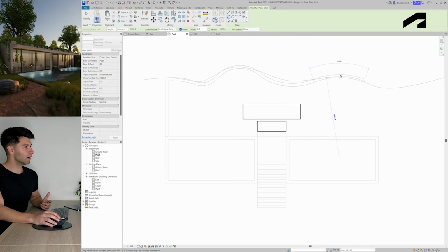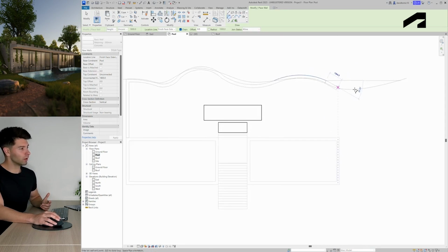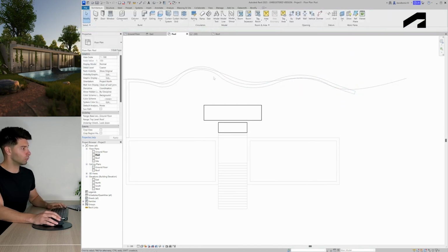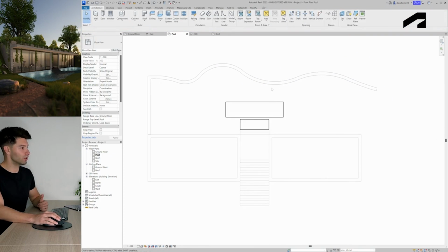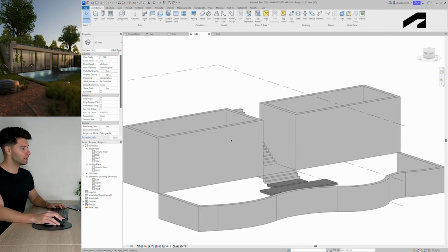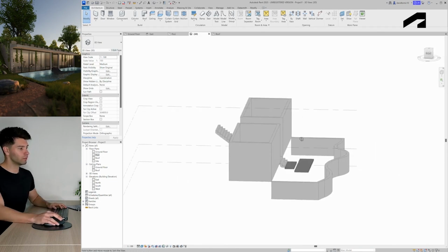So as I'm clicking through this spline tool, I'm making sure that I'm following along and still taking very keen notes of how that wall actually connects and looks like in real life. I can delete that spline because I don't need it anymore. Then I can finish it off by pressing TR for trim, selecting the inside of my wall, selecting my other wall, and automatically trimming that away. Pressing escape, jumping back into 3D to see what we've created. We're coming closer to our actual final product.